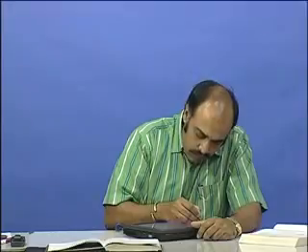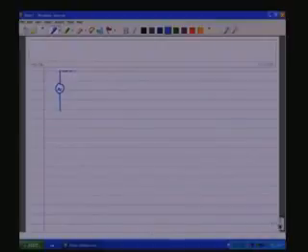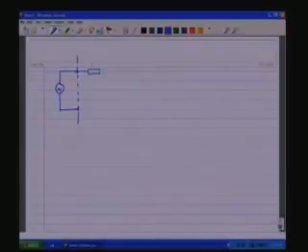So, starting from the equivalent circuit of the transformer, which we have evolved in the last class, we have a source, and this is where the terminals of the practical transformer begin. There is first a resistance R1, which represents the winding resistance of the primary coil, and then you have a reactance, the leakage reactance due to the leakage flux.